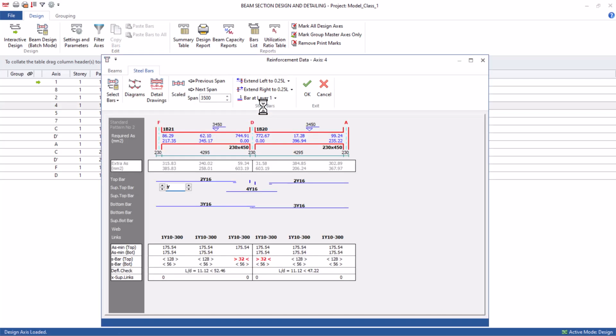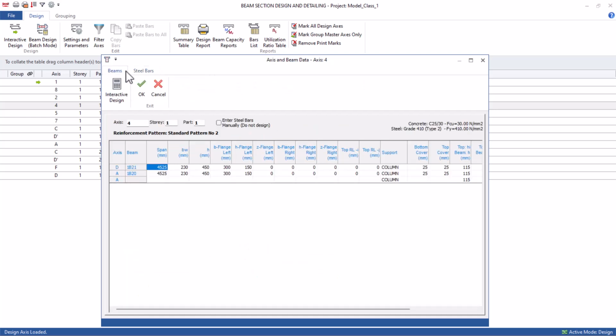So what else can we do to our section? If we've tried increasing the reinforcement and we want to stay within the range of y16 and this is not working, we can try to increase the thickness of this very section to see if that can also help in countering the effect. So to do that, we'll come to this beam here. As you can see, this was designed for a thickness of 450. So this is our H, which is our thickness. It was designed for 450. So let's change this to 600, and I will change this to 600 as well.